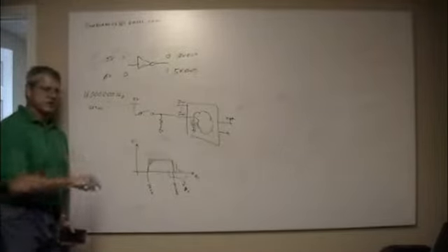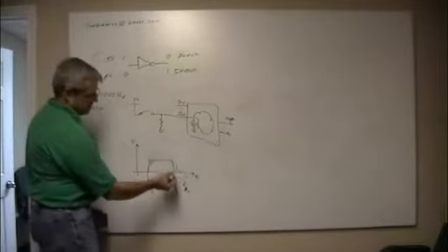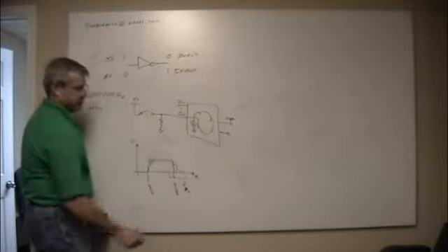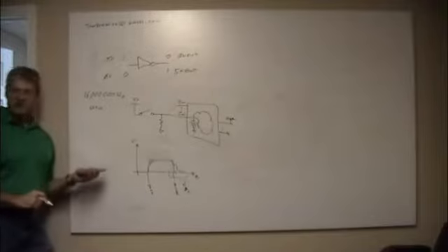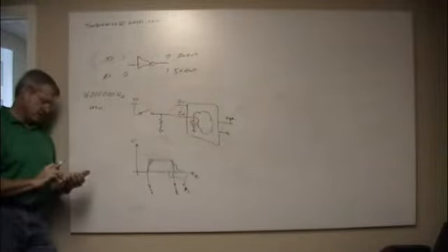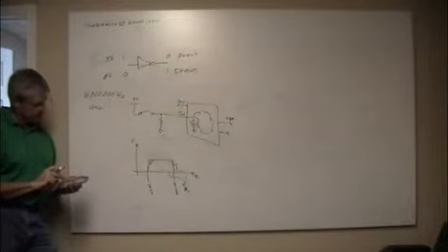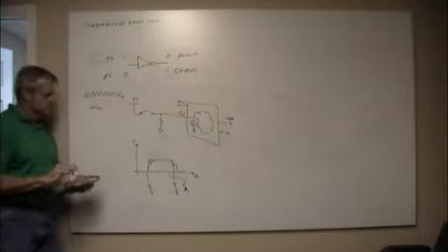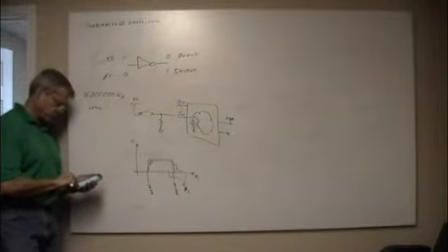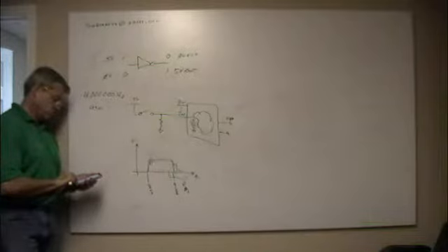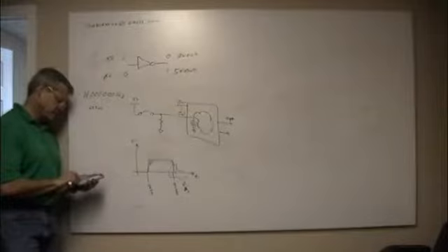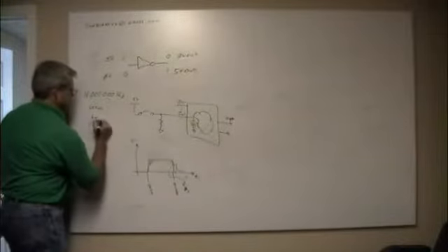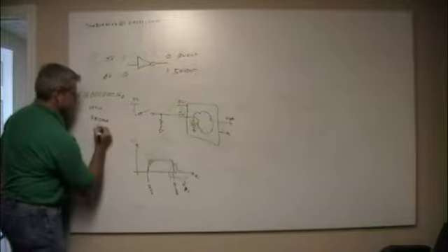What happens if I press a button and this is going on for 3 milliseconds? This is an eternity to this thing. Let's see, 0.003 divided by 0.000000625, that's 48,000 instructions that just happened.